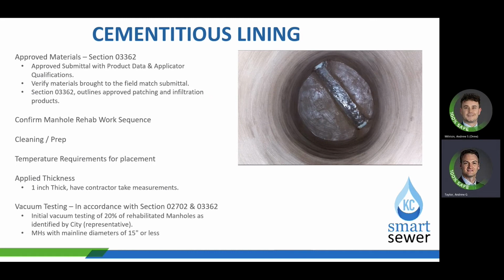So this would be the Permacast Patch 20 or the Strong Shield QSR Plus. Also confirm the manhole rehab work sequence. So with cementitious lining, other rehab should be done before lining. That would be CIPP lining into the manhole, and also the casting replacements should be done prior to any cementitious lining.